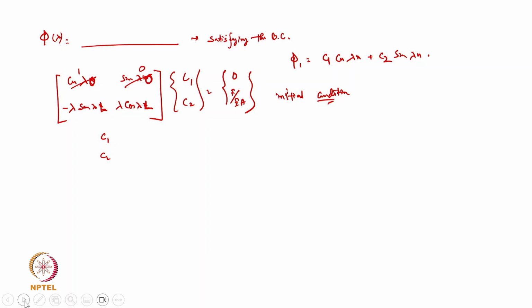But here, what have we solved? Here we are doing the forced vibration. So if we are interested in the transient part of the vibration, then initial condition is required. But if we do not bother with the transient state of vibration, and we are just happy with the forced, steady state vibrations, we don't need the initial condition. Agreed? Which is matching with what we have studied previously also.